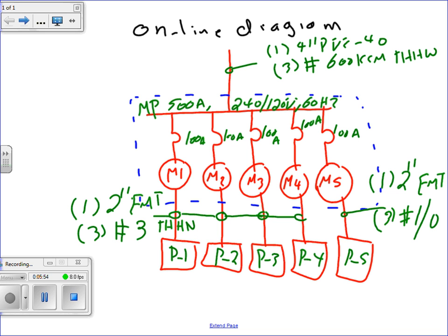You're going to go over... If you were to do that, the messenger. You're talking about the messenger, right? Yeah. The messenger will be used as a grounding conductor. Sure. Oh, you mean the utilities? The one I've seen is grounded, typically connected to the mast, and that's got a big connection going to the ground. Yeah, that's grounded. Yeah, the messenger is grounded.